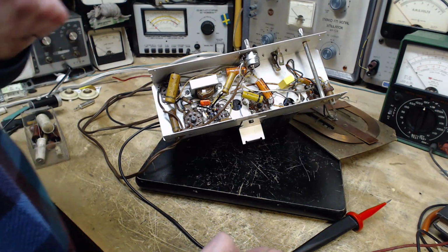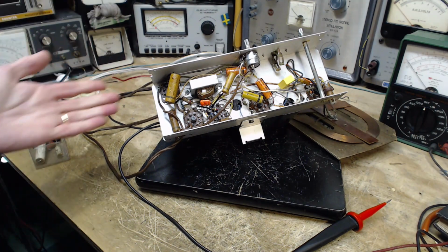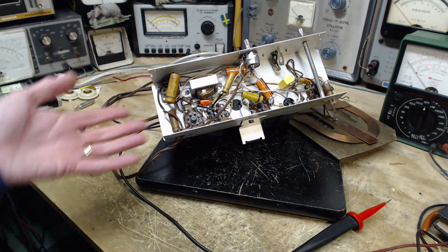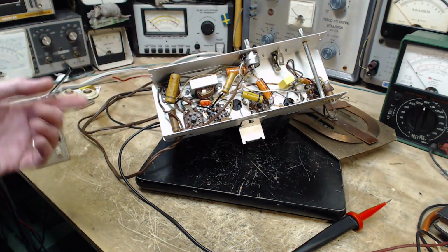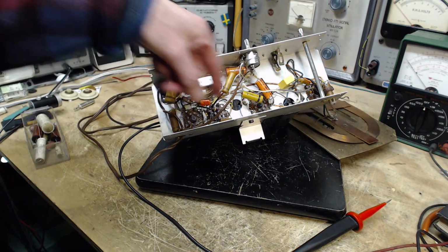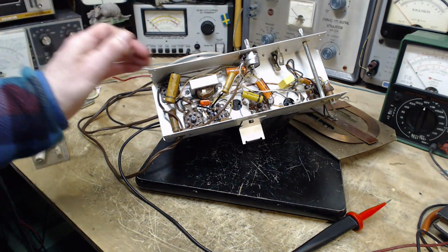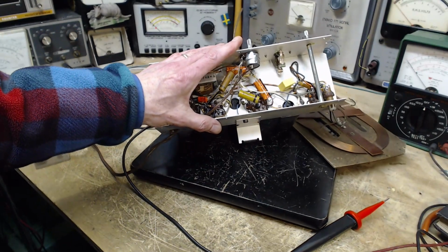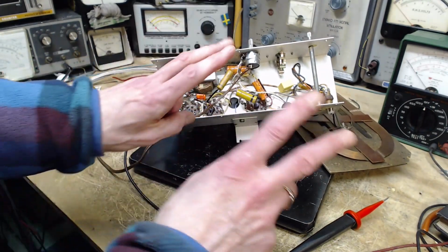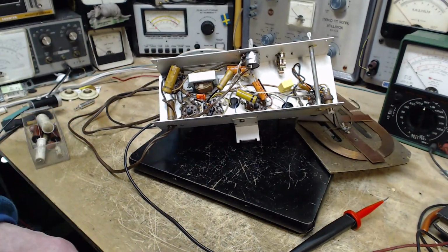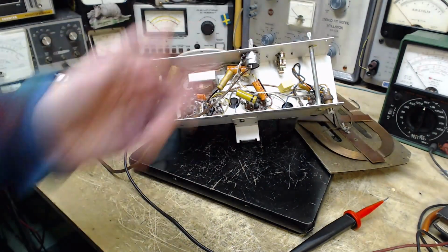And I have had radios like that for sure. Then later on, they figured out that that's just too much trouble. Why don't we just try isolating away the chassis? We'll put a wire in for B minus and run it around in here and make connections. And the problem with that, of course, is the chassis then is a free-floating piece of metal. So let's ground it, although that's a bad term. Let's just tie it back to B minus, and then it won't have any influence on the radio's operation.